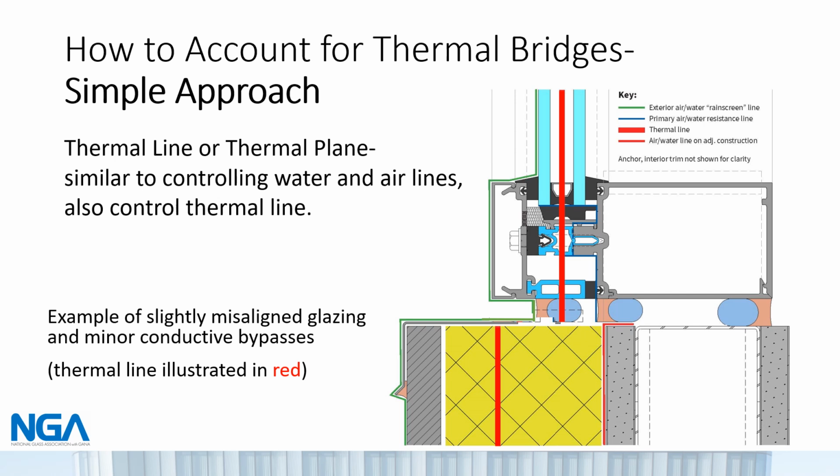The glazing subcontractor and framing manufacturer should be able to determine how water can be drained from the glazing system to the building exterior. Establishment of the air barrier transition from fenestration system to perimeter conditions is equally important.